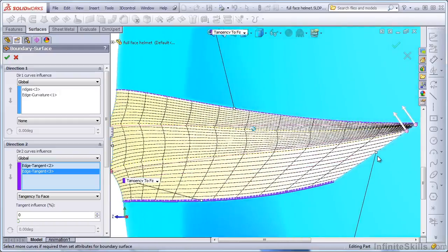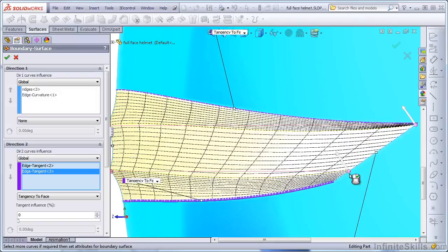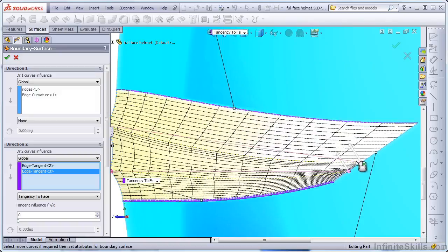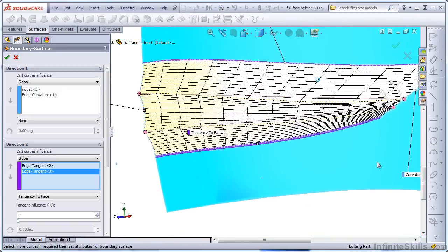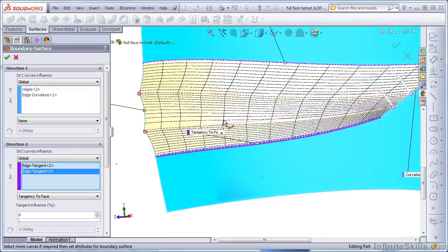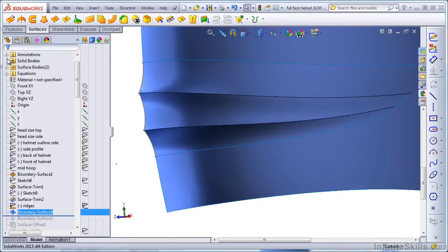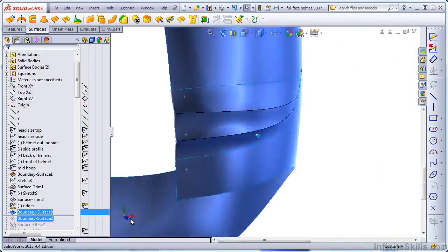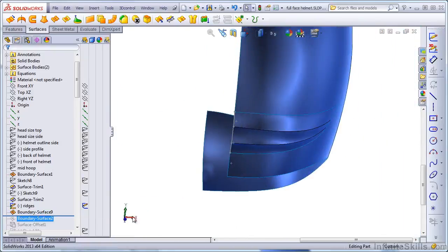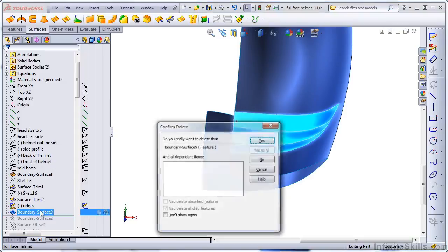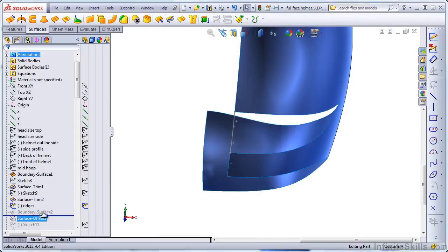Well, in this case, it's working out pretty well. So you can influence the shape nicely by using these connectors. And remember that you cannot use the connectors if you have the selection manager active. For whatever reason, SOLIDWORKS doesn't allow you to show connectors and the connection manager at the same time. So if you want to push these ridges in a certain direction, connectors would be the way to do that. Now let me delete this since we already have a feature that accomplishes that.